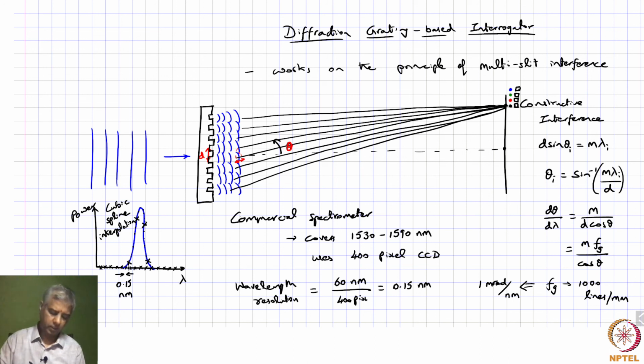So, even if you have say a slightly different Bragg wavelength, even though for that different Bragg wavelength you are picking only these few pixels, if you are doing your interpolation correctly, like if you use this cubic spline interpolation, even if this is only 1 picometer, you can resolve that.